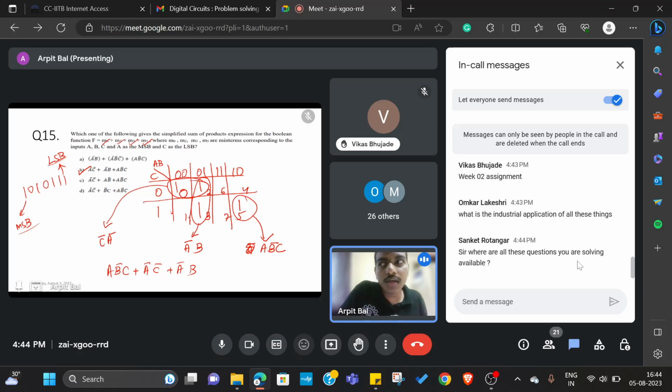Those floating point numbers need a specific hardware, because after the decimal point you don't know how many bits will be needed, right? So you need to make a very flexible hardware which needs to accommodate multiple bit operations, working for 8-bit operation, 16-bit after the decimal operation, and so on. By using these notations and representations, we can make a hardware which does not need that degree of reconfigurability.